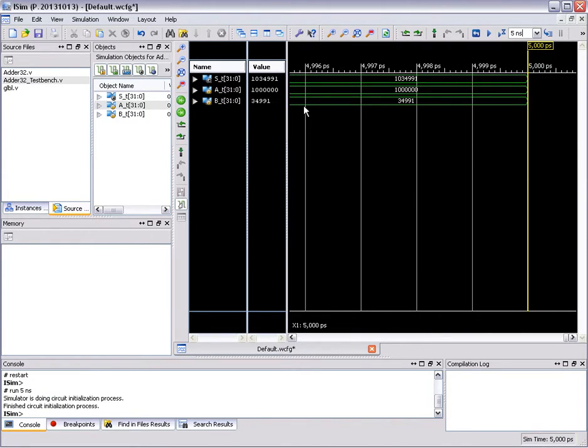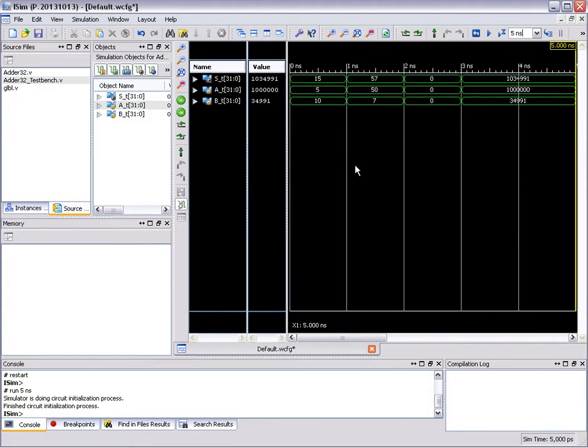So we can do that, and now we can see our waveform is generated here. The waveform is fairly zoomed out, which doesn't allow us to see it very well. So I have a couple options. I can manually zoom out, clicking this button several times. Or the next button here allows us to zoom out to show the entire full view of our simulation. Our simulation was short enough it's pretty easy to see.